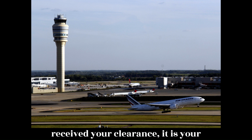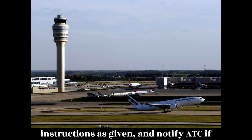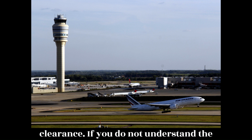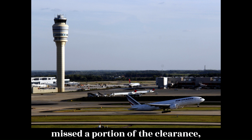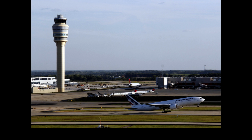Once you have received your clearance, it is your responsibility to comply with the instructions as given, and notify ATC if you are unable to comply with the clearance. If you do not understand the clearance, or if you think that you have missed a portion of the clearance, contact ATC immediately for clarification.